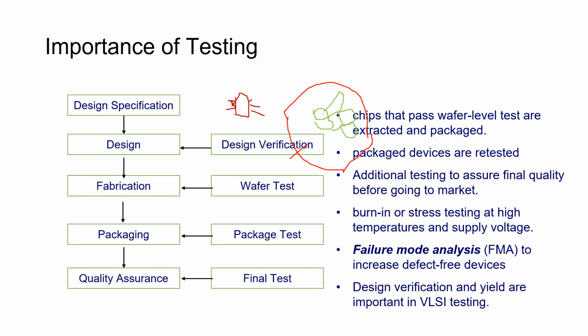We'll talk about it later in a few weeks, or I'll give self-study material for you if you're interested. So that's something called burn-in test. You have to test your chip under stress and in high temperatures. You have to supply very high voltage. You have to test and see how it responds.